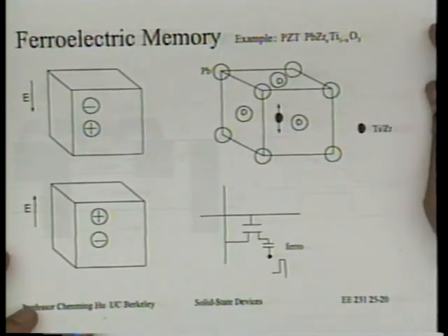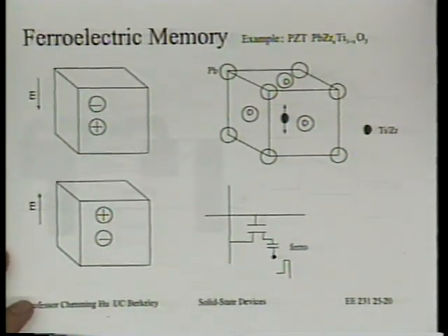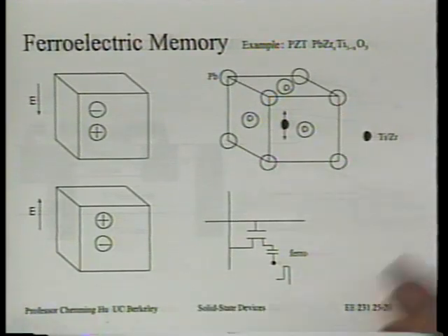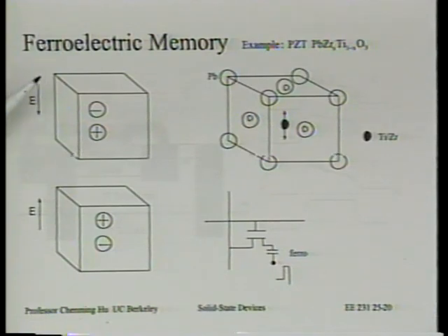And there are many new ideas. I just mentioned one. It's called ferroelectric. Other ideas would involve a magnetic change of property of a film, and yet others would involve some thermally induced phase change of a film. So there are different ideas of looking for new non-volatile memory, but they're all exploratory. The closest to a commercial product is ferroelectric memory, which actually has some low-density memory on the market now. Other than that, floating gate still dominates.